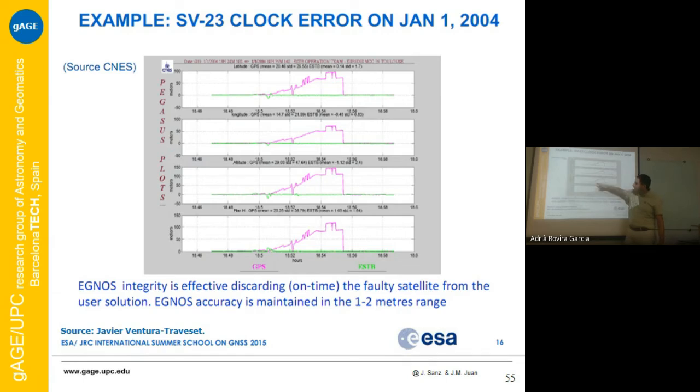And we can see that without any SBAS, without any augmentation system, we had very large errors, but by applying the EGNOS corrections, we had a very nice accuracy. And so it was safe to use the EGNOS solution and the SBAS solution.